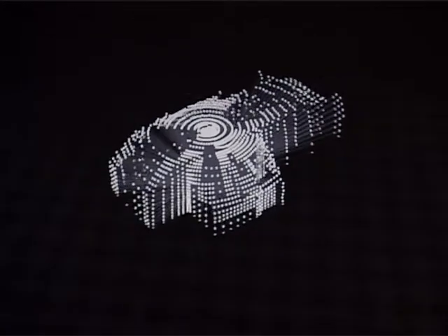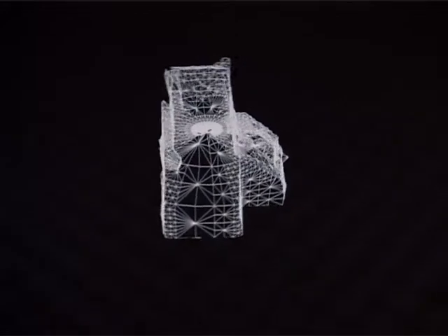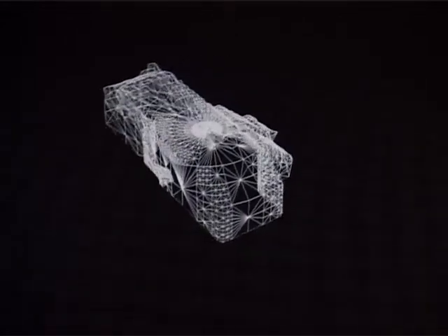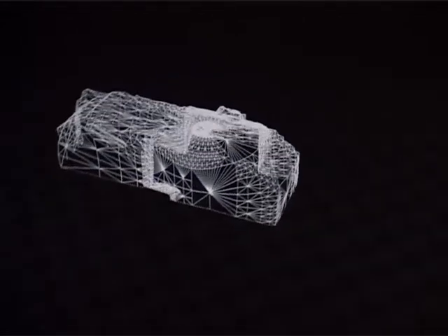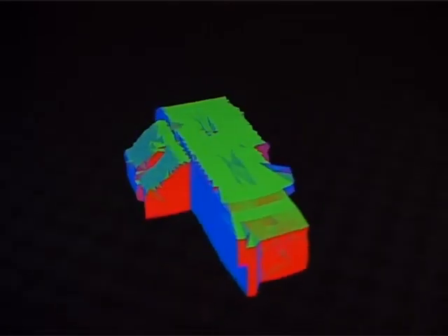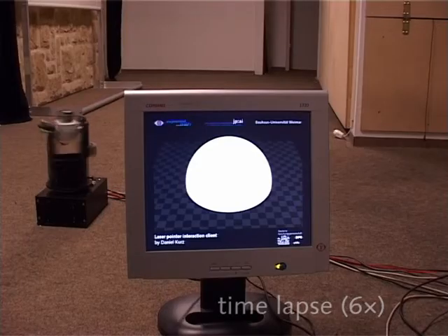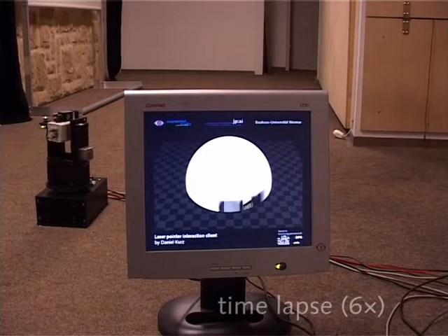This results in a low-resolution sampling for largely planar environmental sections and in a high-resolution sampling for geometrically more complicated sections. The resulting point cloud can be triangulated, intermediate depth values can be interpolated, and normal vectors can be computed. Since the sampled points are measured in device coordinates, the rigid transformation matrix can be estimated numerically by finding the best geometric match between the point cloud and the measured reference model stored in the database.